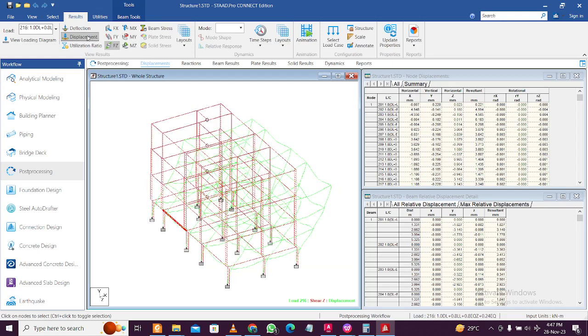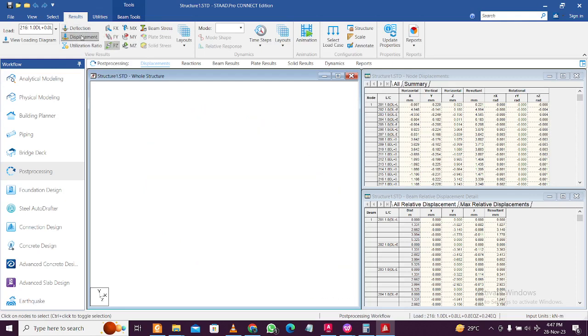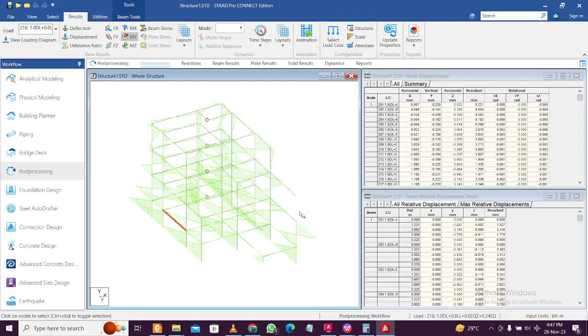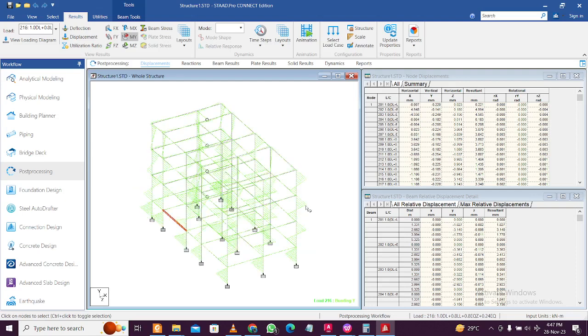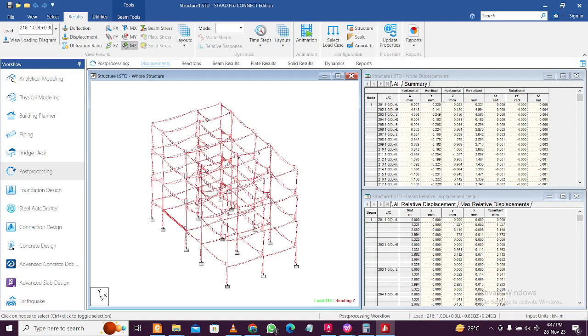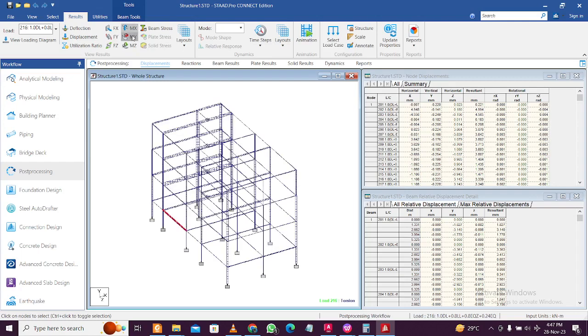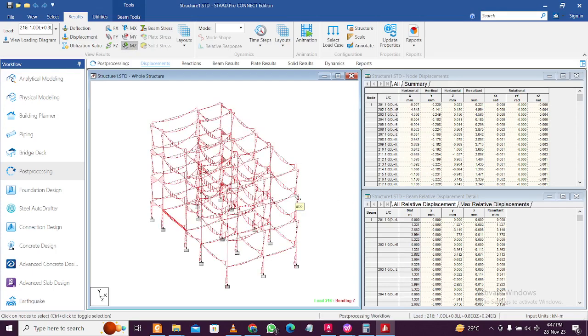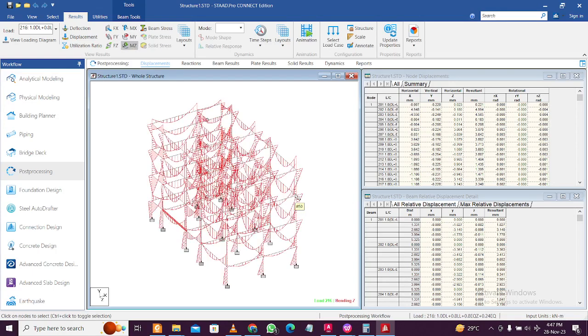Untick displacement here, untick MY. So this is the MY, the bending moments. You can increase the magnitude by pressing control and then this MY, and MZ is this bending moment here. MX you will not find anything, so it is MY, just MZ here. Okay, in the Z direction you can increase the magnitude with control and the mouse wheel.